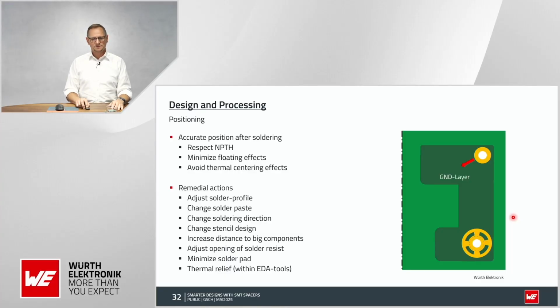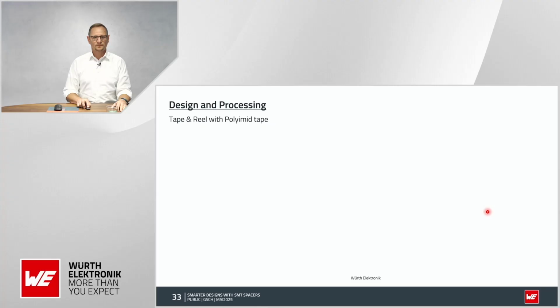I've been talking about the thermal centering effects. If you have a big ground plane, then this might draw it out of the position. There's a solution called thermal relief, and normally you find this function in your EDA tools. So for this pad, you have a thermal relief here, so this one is decoupled from the ground plane.